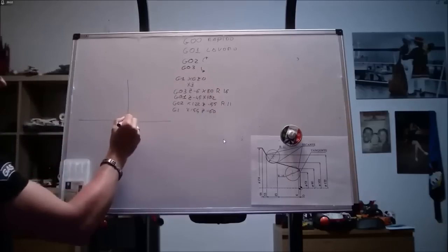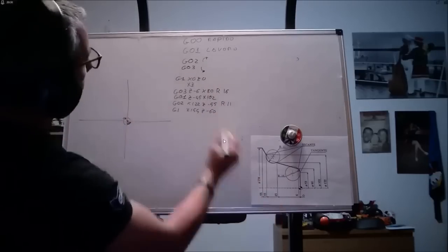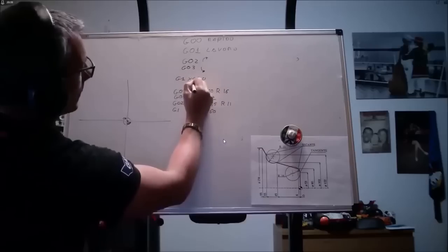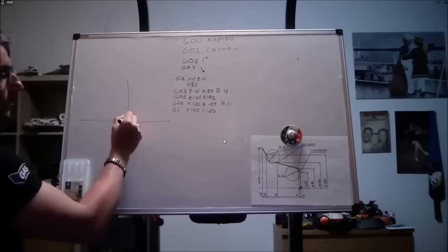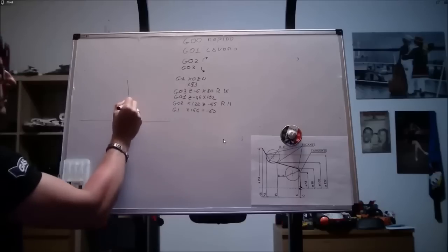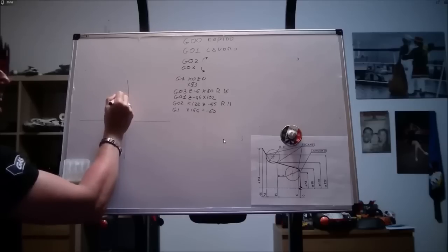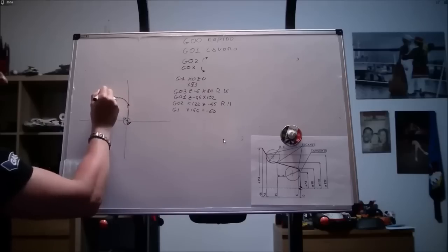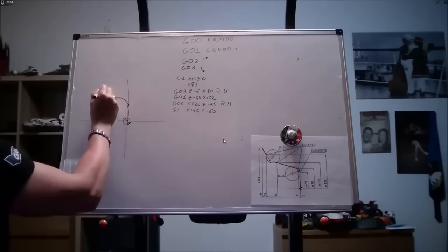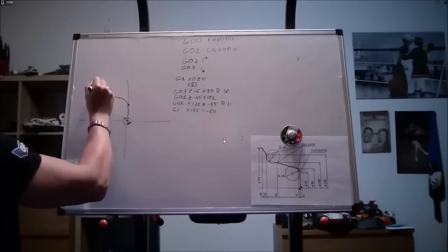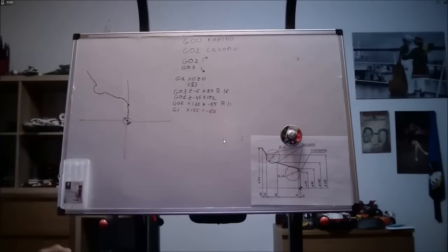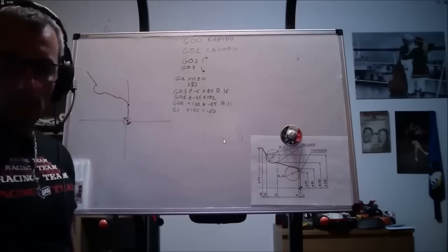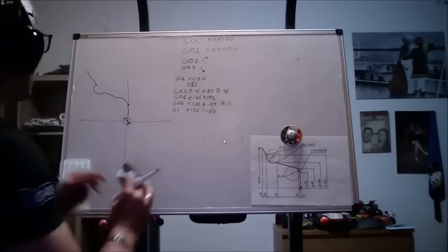Let's read our program. I wrote only 3 here, but it's actually X53. Let's read our program: X0, Z0, X53. Then circular movement to Z6, X80, G1, X102, Z45, G2, X122, Z55, R11, G1, X154, Z66. You see that it is indeed not difficult at all.